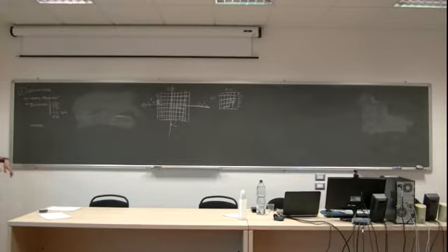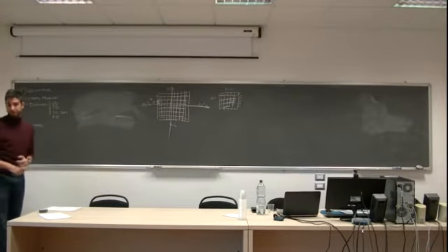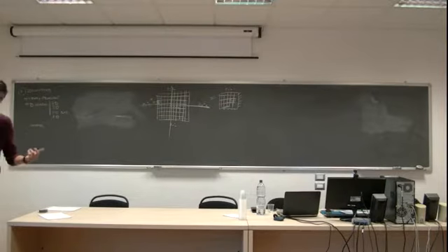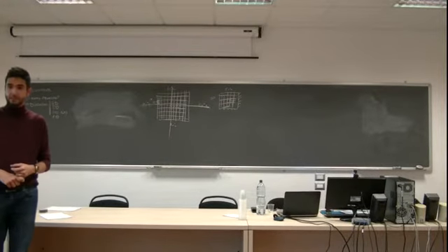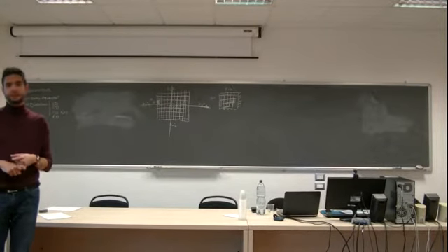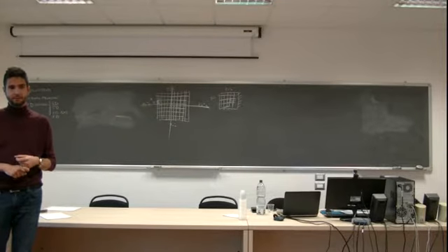Another thing that I think is important: thermophysical properties in your simulations. I know that density, conductivity, viscosity, heat capacity, everything depends on temperature, and pressure if it's a fluid. But is the change very significant?